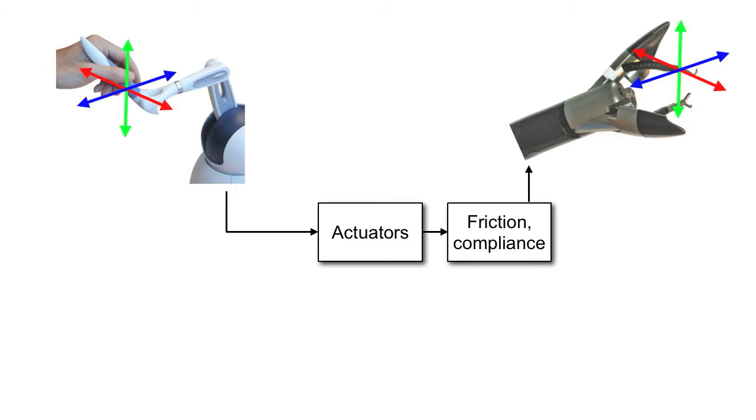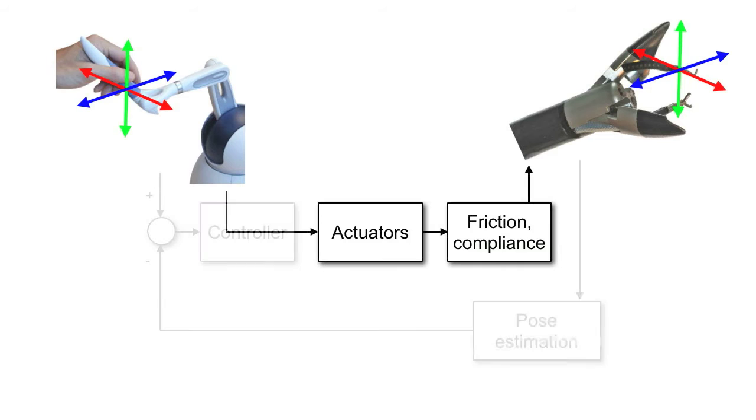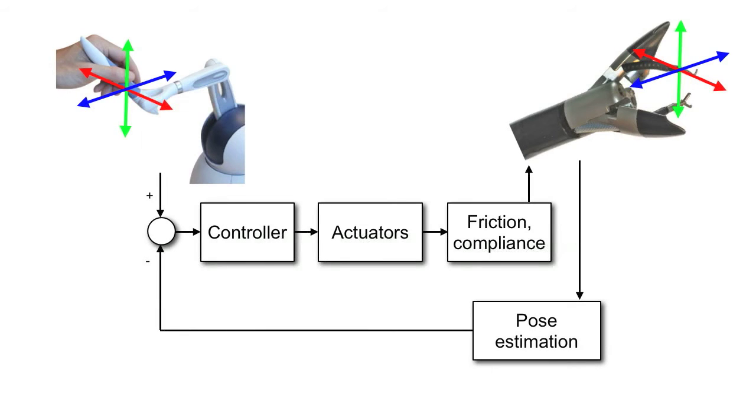However, actuating the instruments is not straightforward, since there is a lot of friction and compliance between the instrument and its actuation point. This causes hysteresis, which prohibits convenient steering. In order to reduce this effect, a feedback loop can be used to control the position of the instrument based on the input given by the physician. Such a feedback loop requires information on the current position of the instrument.